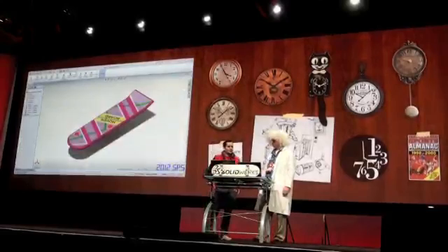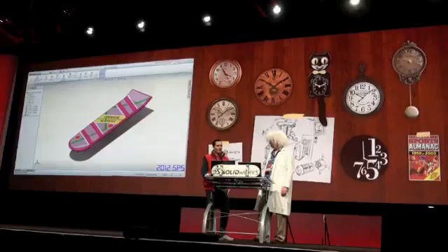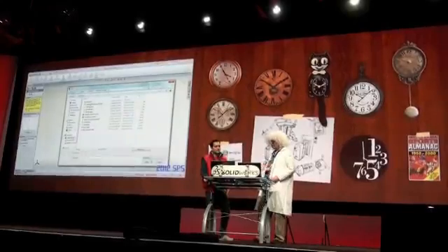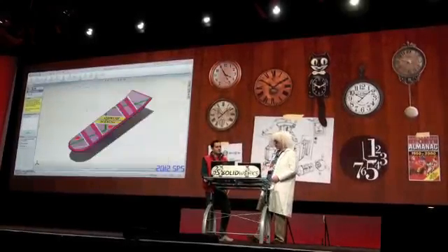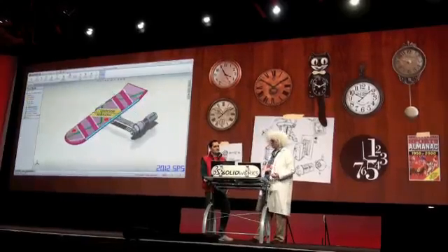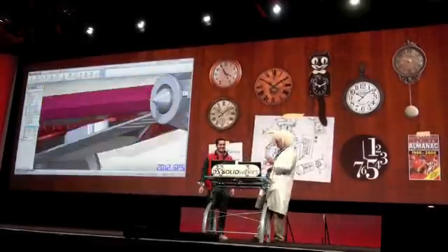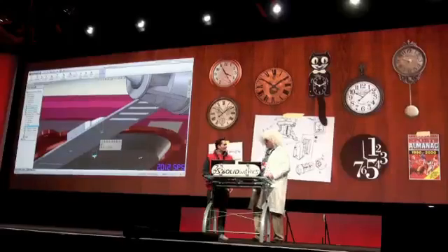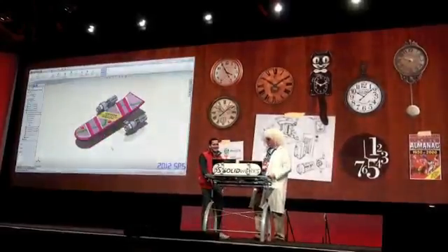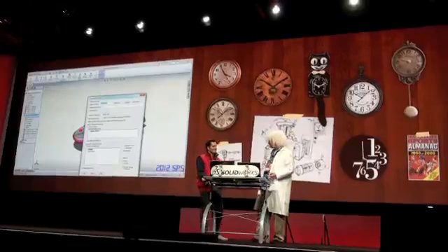You know, I'd really like to have some of those engines on my hoverboard. But the only problem is, I've got SolidWorks 2012 SP5 on this laptop, and I didn't have time to upgrade to 2013. Marty, you don't need to worry. You can open 2013 files in 2012 as long as you're running SP5. Even though they're frozen, you can insert them into assemblies, and things like components, and use the geometry to build a component or a machine around someone else's 2013 model. And what's even better, you even have access to all the different configurations of those future parts and assemblies.